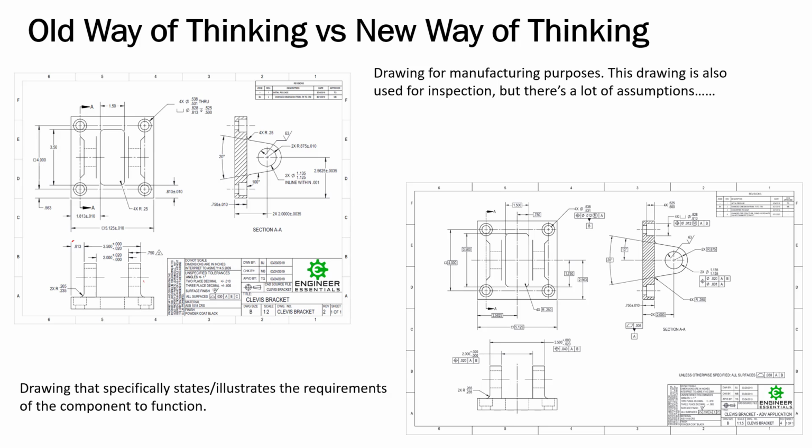So now on the flip side of this, the manufacturer may not know GD&T. So if you are subcontracting this out, and your original question was about vendors and capabilities of those vendors, especially when you're dealing with multiple vendors, you may have a vendor that has a CMM and will give you good results every single time. You may have another one that doesn't have a CMM, and they're doing a lot of this with height gauges and pins and whatnot. And I'm referring to the GD&T print right now.